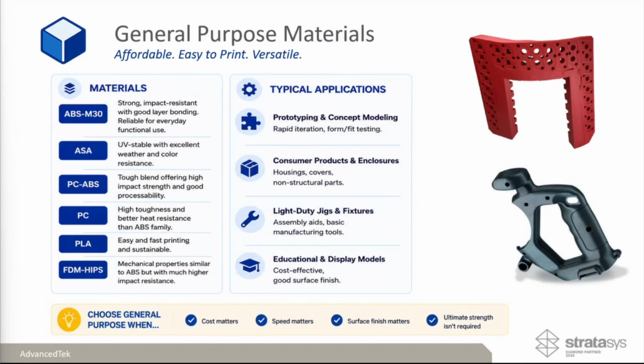Next is your PLA. It's easy, fast printing, sustainable. It's a non-toxic material that's made from renewable resources. Makes it good for educational settings. Has a relatively low cost and prints fast, making it great for early design concepts that can be printed quickly for design iteration.